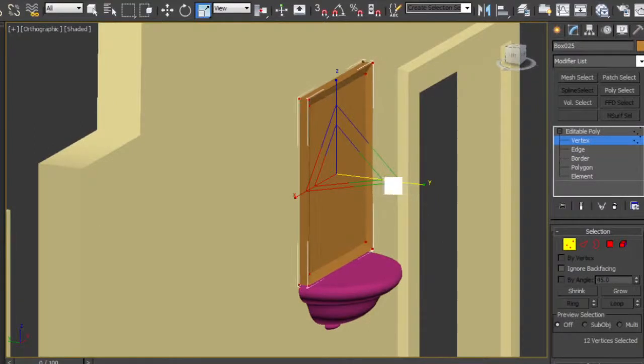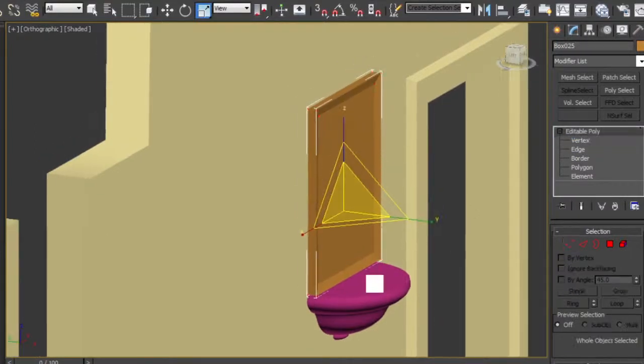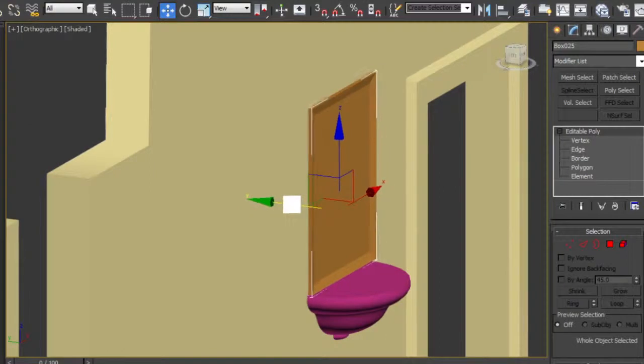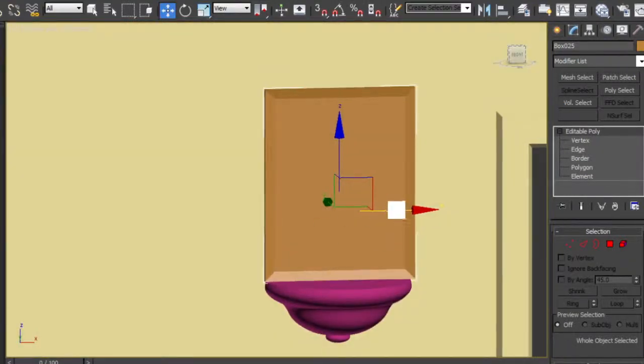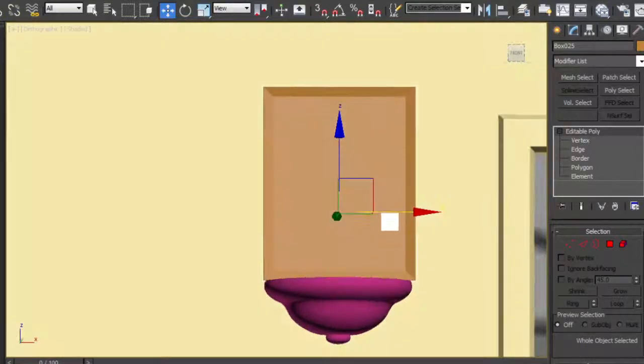Since we want to avoid applying a non-uniform scale to an entire object, we can do it simply at the sub-object vertex level. Get the same results, but no change to the x-form on the object.